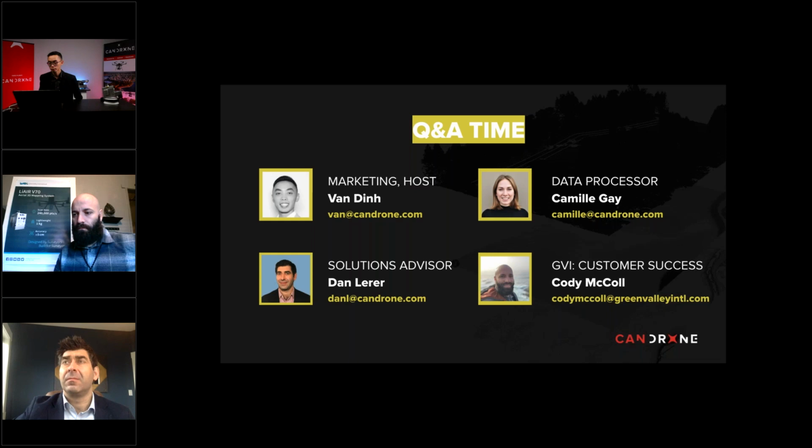If you don't see them when you load in that file, chances are you have the wrong coordinate system. So you might have to convert your GCPs or reproject your LiDAR point cloud in that case. I think, rephrasing the question, you might be asking: if you set out targets in your LiDAR data collection area, how would you be able to visualize that and match it up to see the target? Okay. Yeah, it really depends on the target.